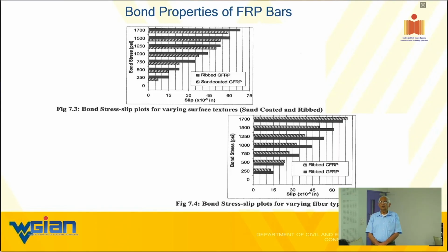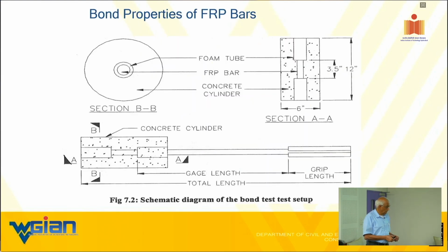Okay. Maybe I didn't explain it well. Why are we wanting to have 40 times the diameter? Maybe I should have addressed that. Why am I talking about this length to be 40 times? You know why? I didn't explain that, sorry. Because we want to minimize the bending effects.